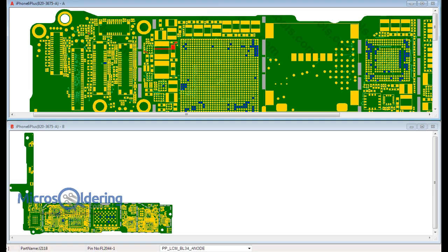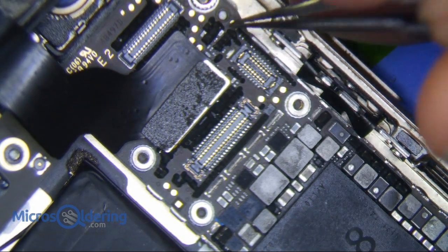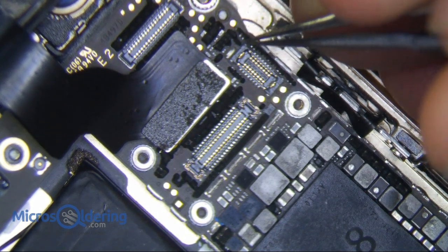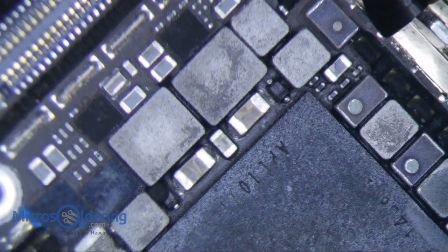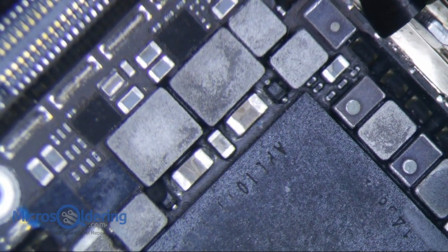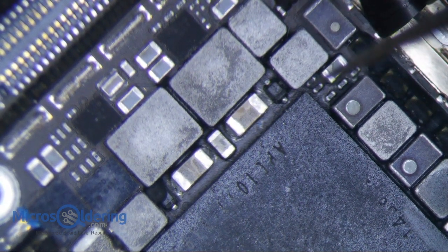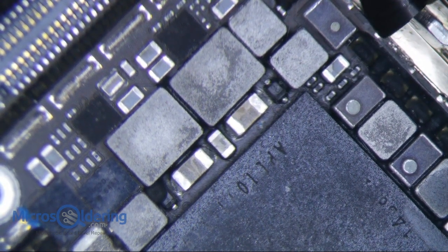And let me go back to my other one. Okay, so we tested this point right here. This is the backlight, the system that is messed up. Alright, so that's the side we're going to trace. So the phone is still powered on right now, and you really don't want to measure anything when the phone is powered on. I mean, you really just want to measure voltages. Okay. So let's turn the phone off.